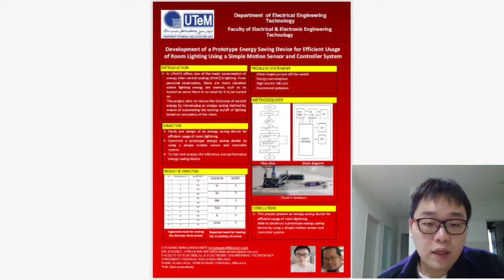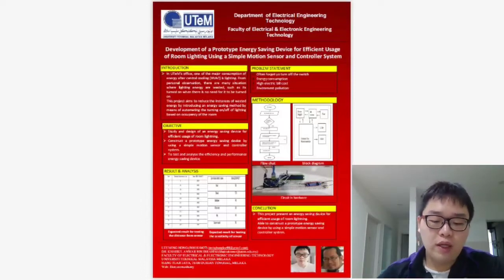The second is 25 cm, the third is 50 cm, also on, until 200 cm, which is 2 meters, the LED is still on. At 225 cm, which is more than 200, the sensor turns off. So our sensor can detect up to around 2 meters.